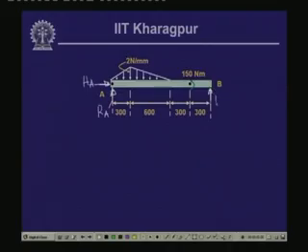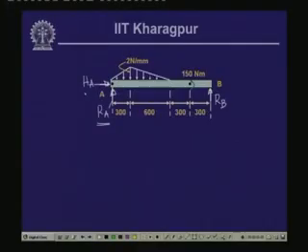the vertical reactive force over the roller, which is R B. Since in the horizontal direction it is allowed to move, there is no horizontal force component there; we will have only the vertical component. Also, since at both ends the beam is allowed to rotate, there is no need for any moment to hold this rotation back, hence there are no reactive moments. So, the three unknown reactive forces are H A, R A and R B. These three unknown quantities are to be evaluated from the given loading, employing the equations of statics.